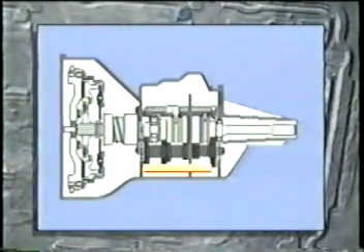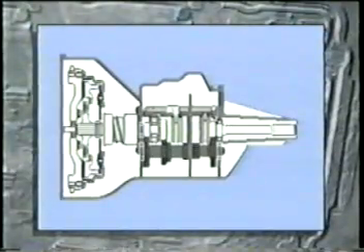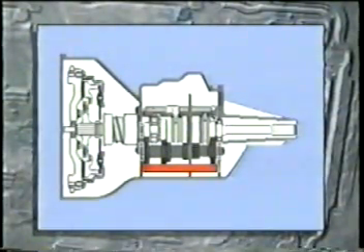Inadequate preload will allow the shafts to move and may cause the bearing races to spin in the case, resulting in noise and component damage. Too much preload may cause the bearing to overheat, resulting in noise and premature wear.